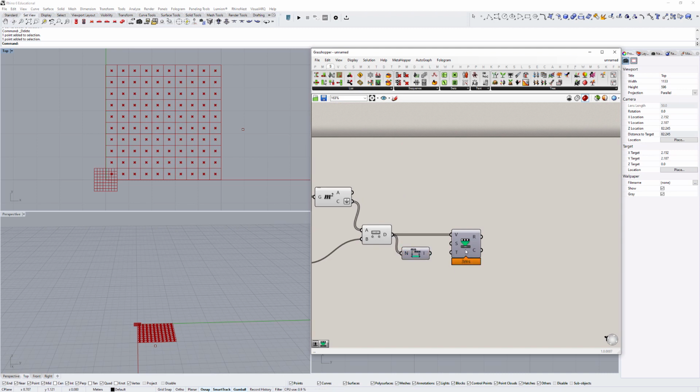So if I put in D distance into N for our numbers, hover over the output, and you can see that our minimum number is 1.19 and our maximum is 6.24. Let's put that input I into S. So more often than not, you'll probably use or see the remap and the bounds used together.